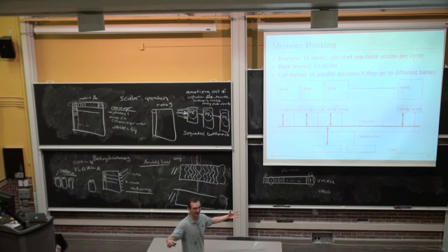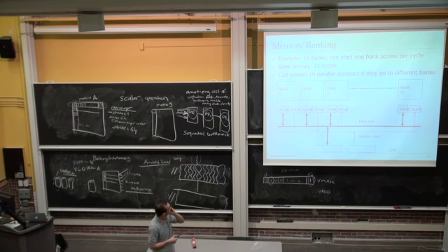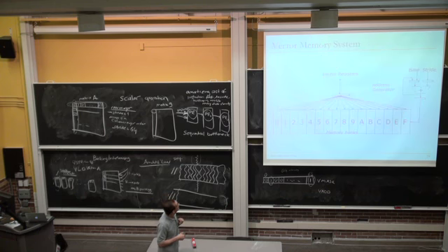That reduces the bank conflicts quite a bit. But that's, again, how do you index into that, right? How do you map the data? Okay, this is some food for thought for you. People have actually devised mechanisms that randomized the mapping between a physical address and its location in the banks to reduce the bank conflicts also.